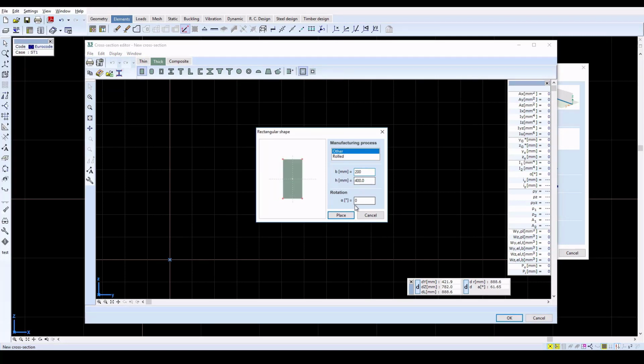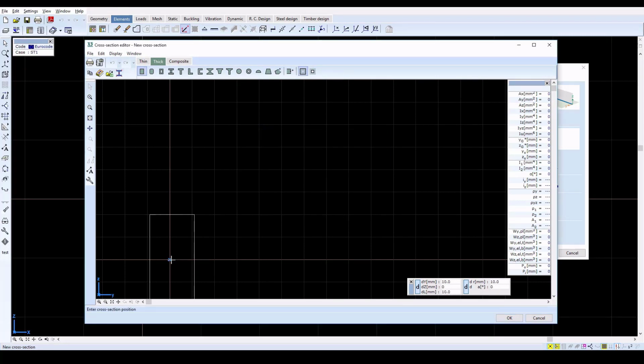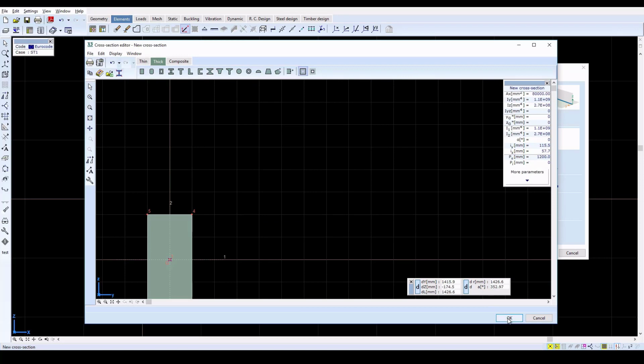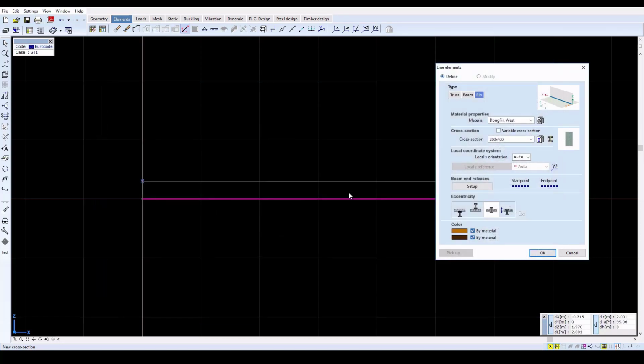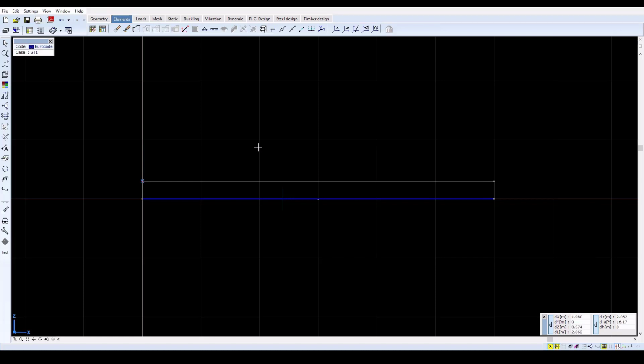Since the line-to-line link elements, which are 2 by 3 node distributed spring elements, are intended to be applied to the model for the interlayer connection modeling, the beam members of the two layered structure should be modeled by rib elements, 3 node beams.